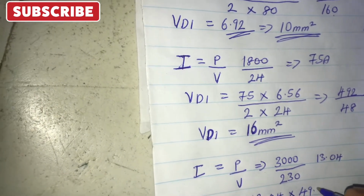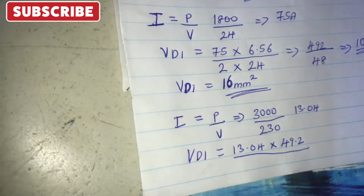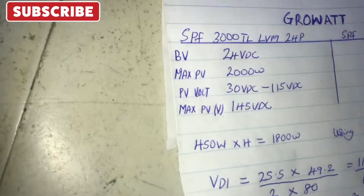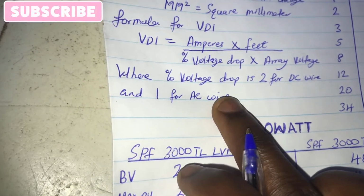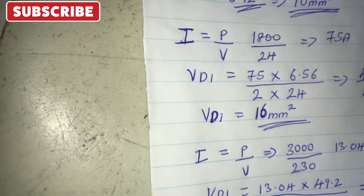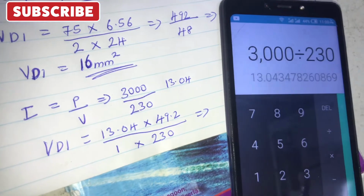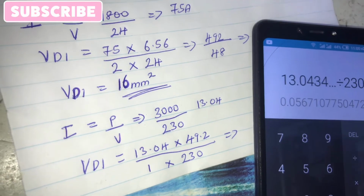which is 49.2 feet, 0.2 all divided by 1. Remember, when calculating for DC, you use 2. That's for your voltage drop. But when calculating for AC, you use 1. So that's why I'm using 1 here, multiplied by the voltage, which is 230 volts. Using this, we'll have our answer divided by 230.